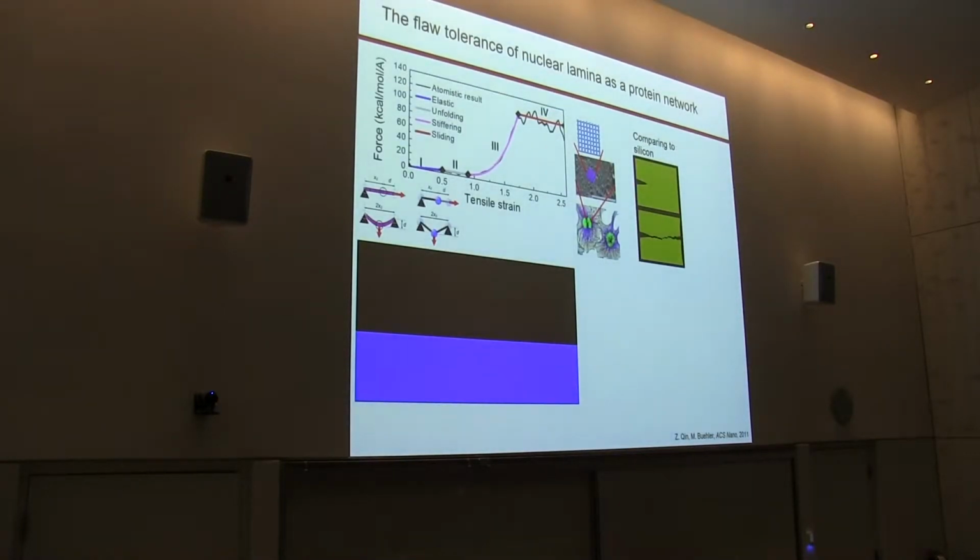So based on this kind of full atomistic simulation, we can extract the stress strain curve for different materials. And then according to the stress strain curve we get for this protein material, we can design coarse grain models. The idea for those coarse grain models is we generalize these protein bundles by using a series of particles as the representative of these full atomistic protein bundles. And then we assign a nonlinear spring between the neighboring particles.